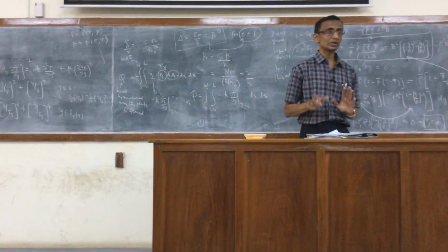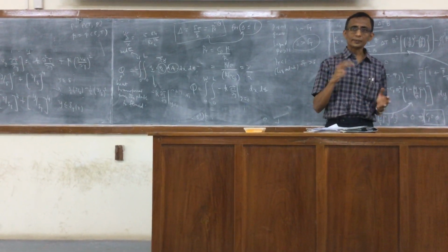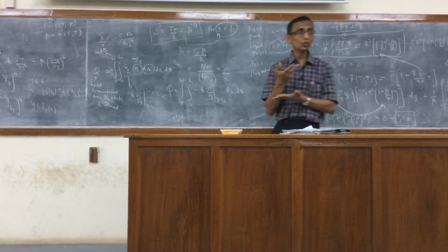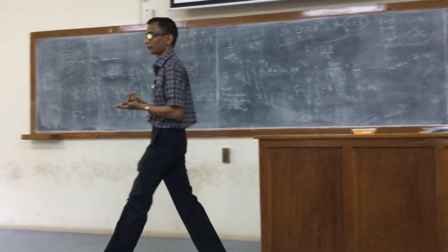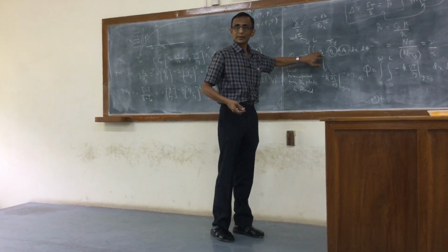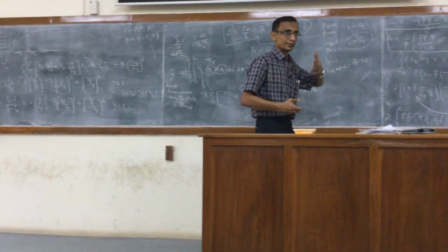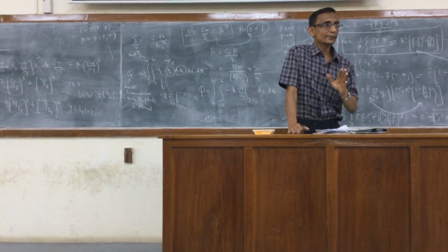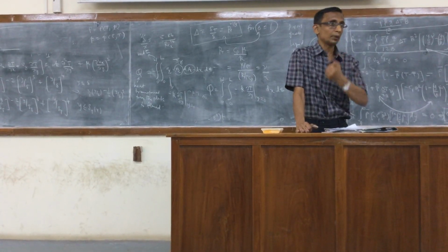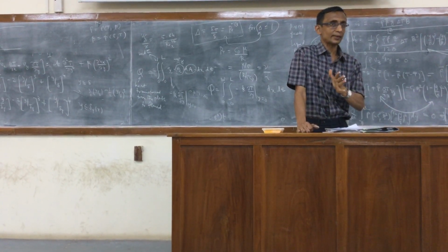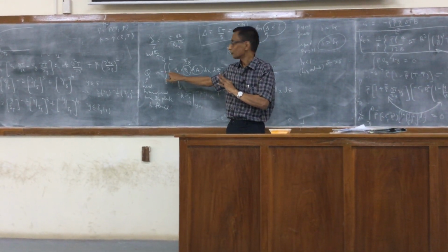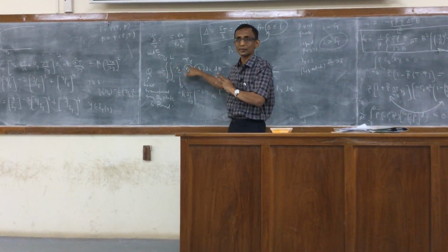forget the sign. Sign convention, there is a sort of a mismatch, because when we say heat input to the fluid, we read that as Q being positive. But on the other hand, the Q, the heat flux vector, is representing the convection heat transfer across the surface, right? That is such that minus Q dotted with n will give the heat input, n being the outward normal. So you have to understand that convention, and it is that heat flux vector which gives the heat input because of this negative sign.